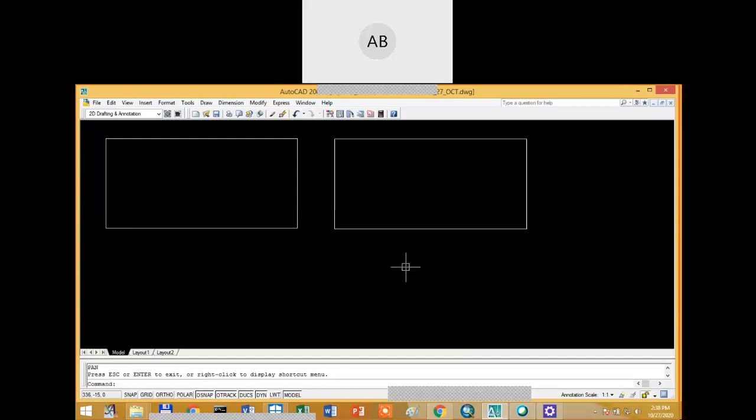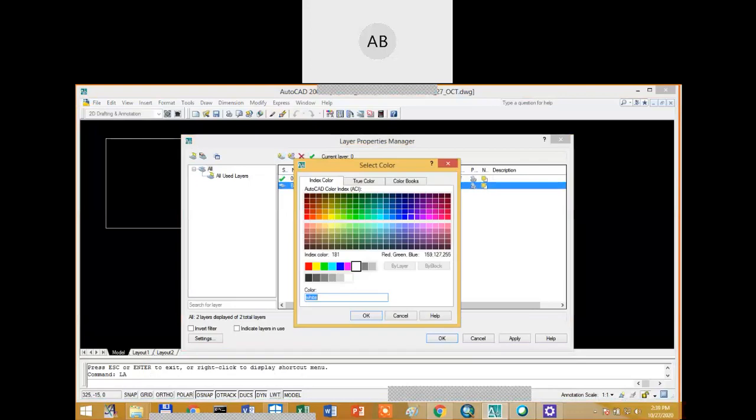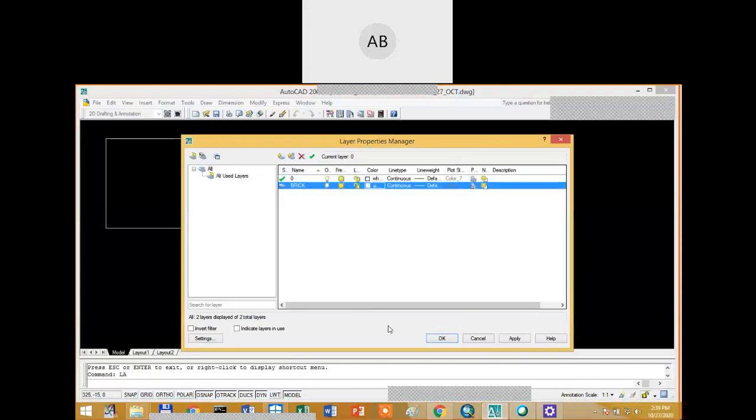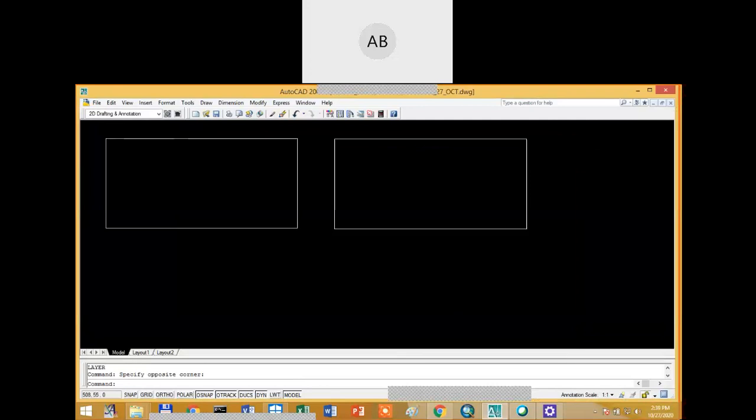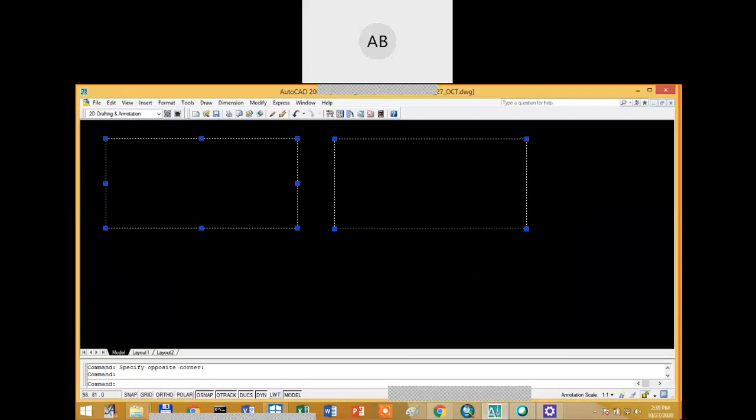Okay, so for a better assessment, I can use a layer command. Turn layer on, LA. I can make one new layer. Go to new layer, name it BRICK. And then I make a color, any color, maybe this one. Okay, apply.